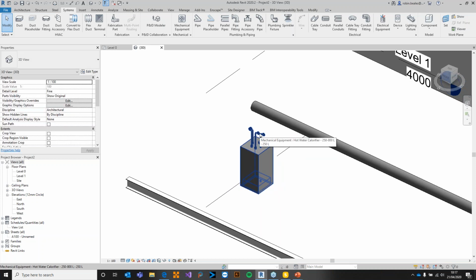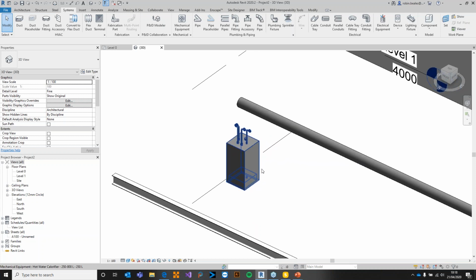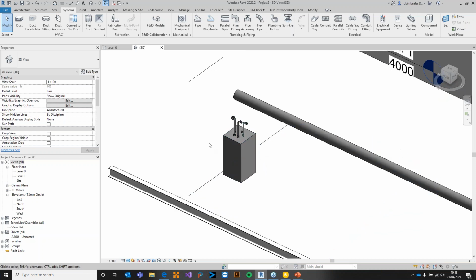You can even go as far as to do things like, okay, well, I've got a curtain wall panel, but that panel's actually a door, or it's actually something else that isn't just a generic curtain panel. Again, you can, at an item level, override what it is so that it exports correctly into the IFC. It means that anyone that's using that IFC to produce ITOs, produce standard takeoffs, or do anything like that with, it's going to give them a better quality result.